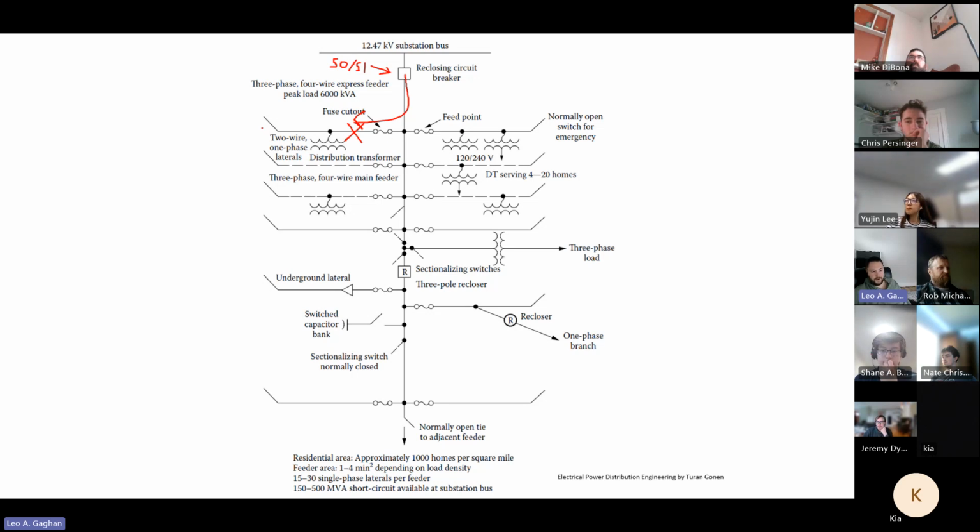These guys unfortunately lose power, but they had to. They were on a faulted phase. And then hopefully if you live over here in one of these houses, you didn't lose power. That's the goal. Same with this recloser that they put in down here. It looks like the whole goal was to break that backbone in two. Same thing, fault happens here.